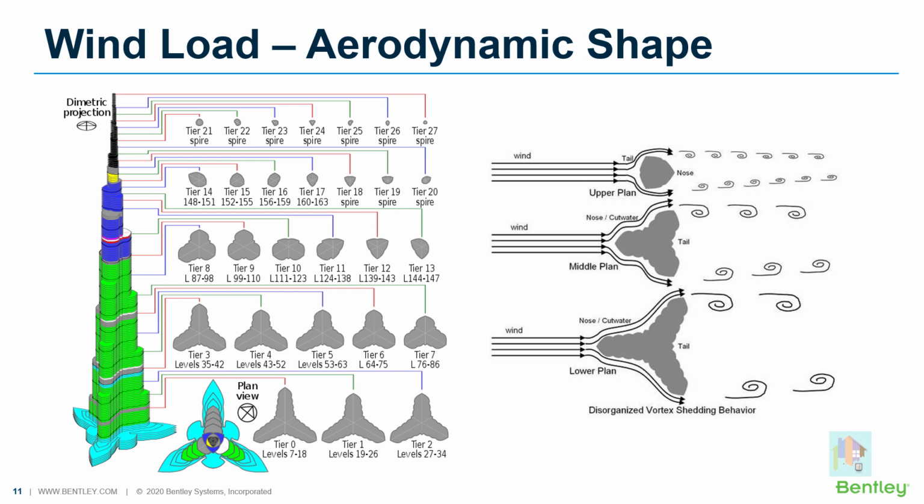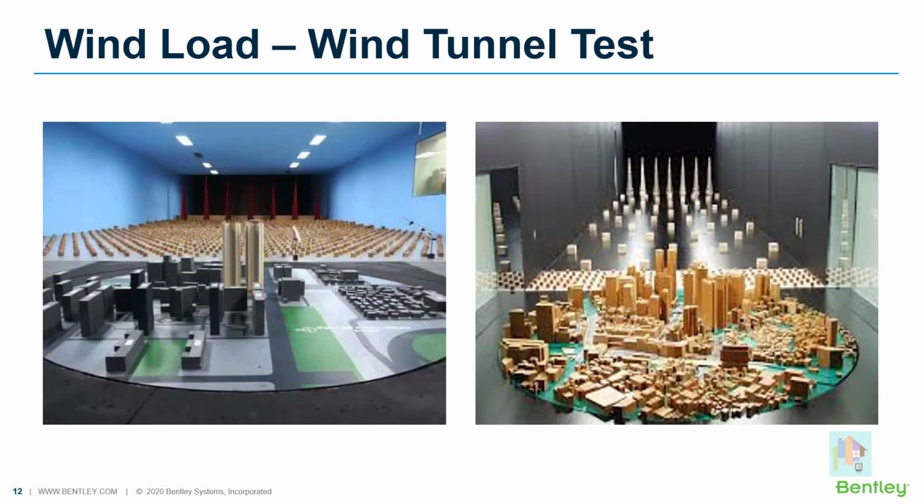To capture all these wind effects on a tall structure, a detailed analysis is required, which can be achieved using the wind tunnel test method. In a wind tunnel test, a scaled model of the actual structure is created along with other obstacles and buildings present in the nearby catchment area. The scale factor of the miniature model depends on several criteria. And finally, scaled wind force is applied on this miniature model and structural response is recorded.